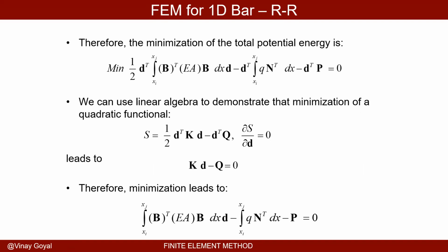they're connected at all. Because one of them is based on energy principles, the other one is starting from the equilibrium equations themselves. The weak form Galerkin starts from the equilibrium equations, multiplies it by the weight function, integrates it by parts to develop the weak form, and that's how we formulate the element. While for Rayleigh-Ritz, I start with the functional. The functional comes from the potential energy of the system.